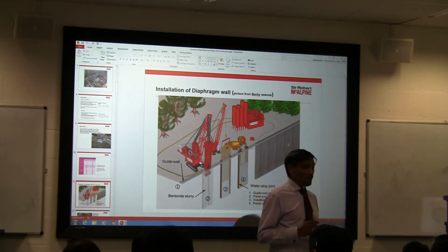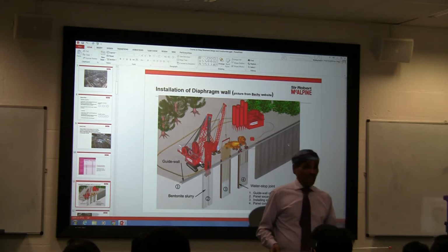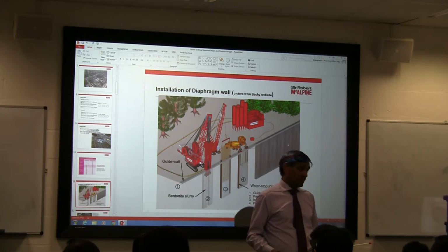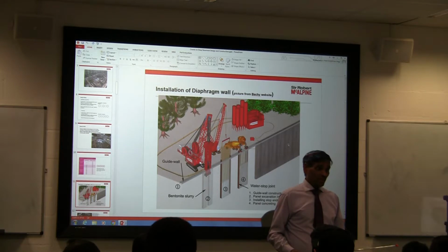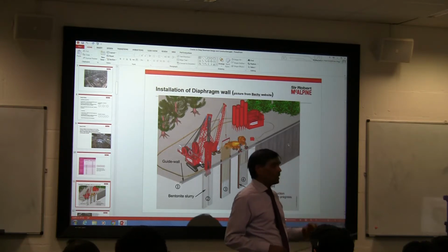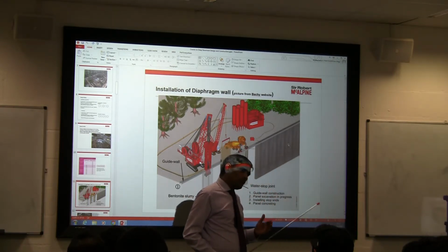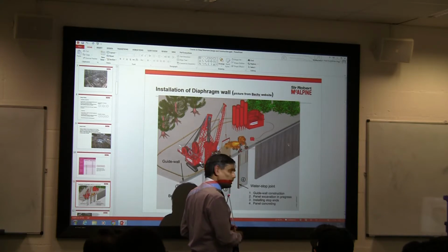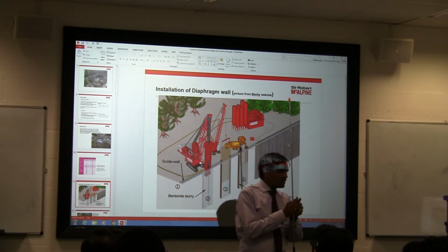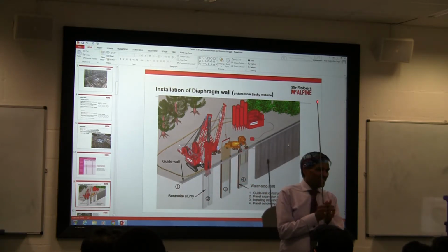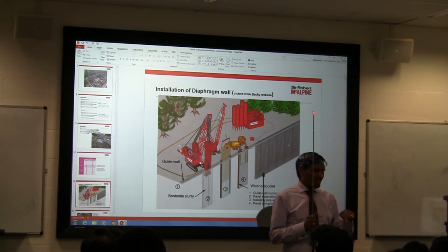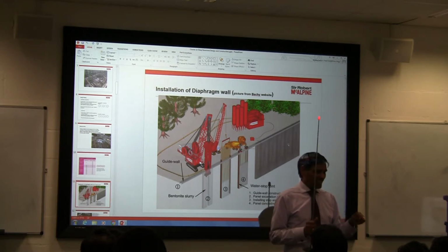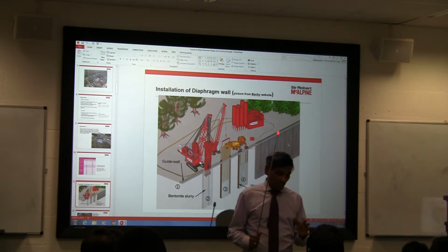I am looking at half a dozen jobs where I have to dig 70 meters for a shaft. 70 meters. Yeah, this is one of the HS2 shafts. So 70 meters. How do I know at 70 meter depth I got interlock between the piles? Remember, I'm going to dig, and I know it is water bearing strata. So you can't take any risk.